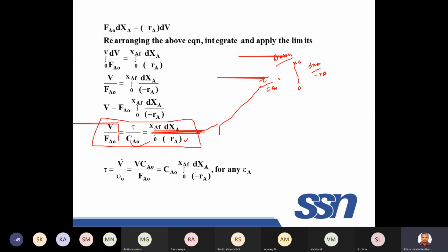Whereas in a batch reactor, there is no input, there is no output. That is at a steady state, I mean to tell, right? Initially, there will be input and you are letting it react for some time, and then you are taking it out. Even though one is a batch process and another is a continuous process, the design equation is the same.